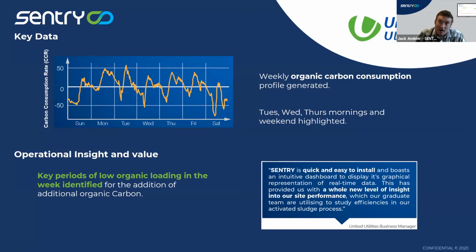So we could see, all right, with this percent increase, how much does that affect the influent? How much does that affect the effluent? Is there actually capacity in the system, or are we seeing some of that material pass through the system? So getting a sensor at the front and at the back end was quite nice for the facility. And then also, as they've started to ramp this down a little bit, as they've experimented on that, we've been able to quantify that and see some of these levels going back down. So I think we were able to see quite an interesting loading pattern for them, understand when they should add material, and then understand, when the problem actually came through, what to do with it.